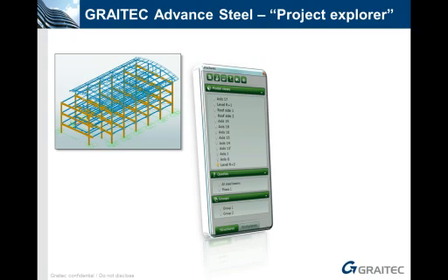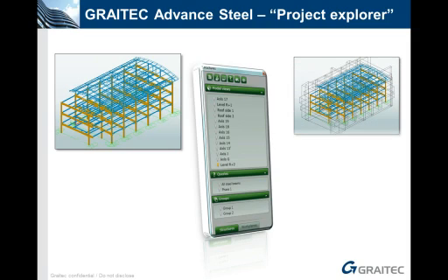In addition, you can also create some queries, specific search filters, and you can even group a part of your model in different groups. And the result is that you can see the different groups, the different model views in your model, so you can display or hide them, and you can just with this bulb here, as you can see on the Project Explorer, display one of them.